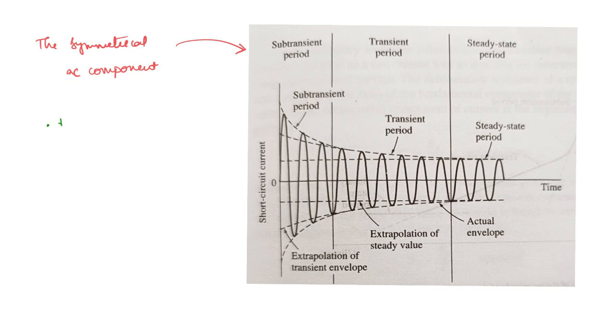We have something called the damper winding, and of course we have the field circuit. Now what is this damper winding? We will discuss it a little more in detail later, but for now you need to know that this winding will ensure the stability of the machine. It will ensure that in case of any transients or disturbances, the machine continues to run at synchronous speed. This is used to maintain stability. So this is the case of a synchronous generator.